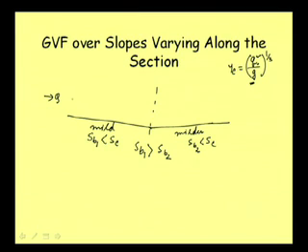So, if I try to draw the critical depth line, I can draw it like that. Say this is CDL, suppose YC calculated is like that, and this depth will remain the same here also, CDL line. So, this is our CDL. Okay. Now, what about the normal depth line? Well, so normal depth line here, as SB is less than or equal to SC, it is mild slope. So, normal depth will be above the critical depth line. So, here suppose our normal depth line is this one,